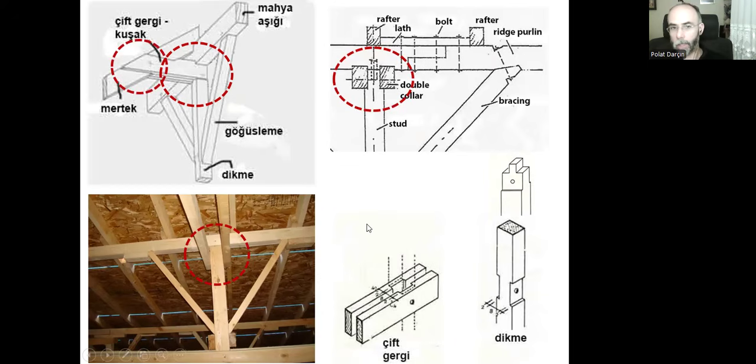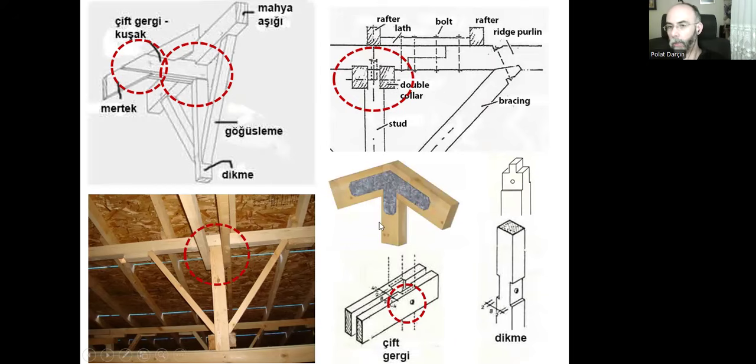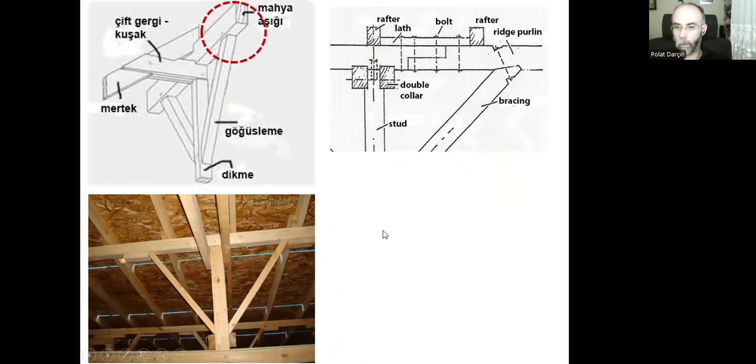And here you can see the collars that are next to the rafter, like that, and they are bolted. We can use these thin steel sheets to hold the bolt, and that's how we can connect a bracing and the intermediate purlin or ridge purlin. Again, we can groove them like this, or here in this example, they use these little pieces so that it won't slip sideways.